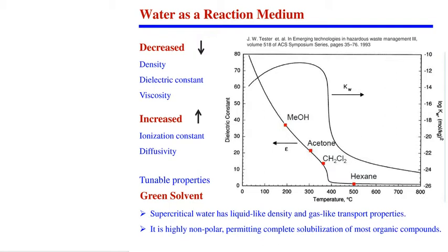It is not dependent on the type of biomass. Any type of biomass we can use with this. It reduces mass transfer resistance because of the lower density and many other properties which I talked about earlier. There is flexibility for the type of fuel: we can carbonize biomass to make solid fuel like char, liquefy or gasify. Product separation is easier because we are using just water, not hexane or any other chemicals.